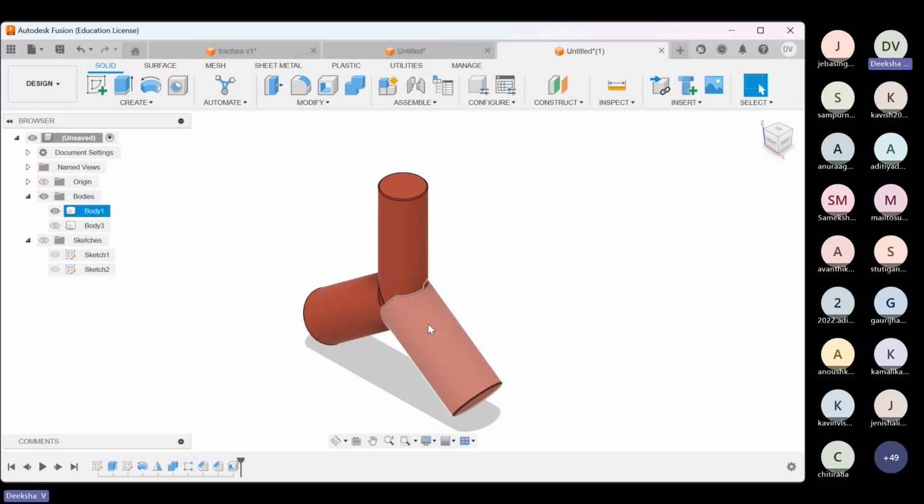Okay, if there are no doubts. So you can see your timeline here. Now your timeline has slowly increased. It shows you each and every step. So first we created a sketch. We extruded the sketch. We created another sketch. We revolved that sketch. We mirrored it. Then we combined the objects and we used the rectangular pattern option. Then we chamfered and filleted these parts.